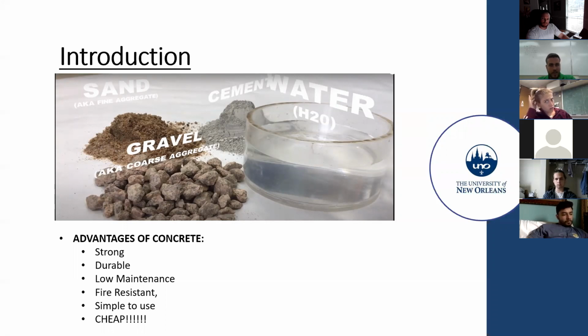Each ingredient in the concrete has a specific role to play, and cement's role is to turn the concrete from liquid to solid. Portland cement cures not through drying or evaporation of the water, but through a chemical reaction called hydration. The water actually becomes a part of cured concrete. This is why you shouldn't let concrete dry out while it's curing.